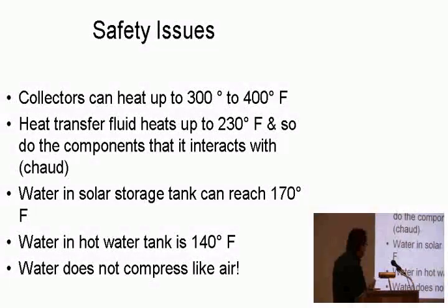Safety issues. Collectors heat up and they get hot, obviously, and regular flat plate collectors will get up to 300 to 400 degrees Fahrenheit. So if you're working on one of these solar systems, it's not advisable to touch anything at the top of the collector unless the collector is covered, but they will get very hot. The heat transfer fluid can get up to 230 degrees Fahrenheit, so it will burn you. And all the components in the pumping station or the piping, any of the metal fittings, will also get hot and can burn you. It says right there, show.